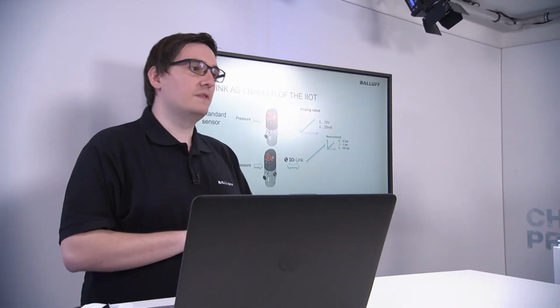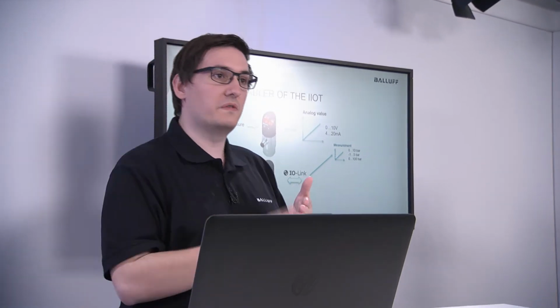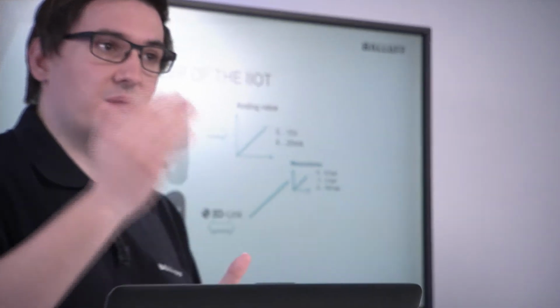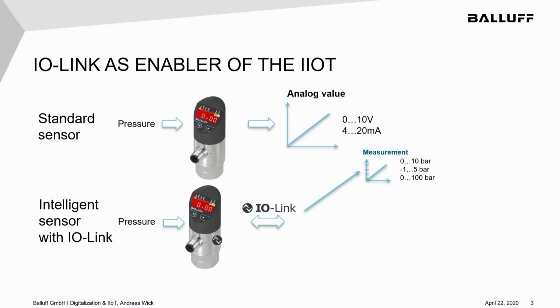As an example, an optical sensor which provides you with a switching signal is very good because you can detect whether there is an object or not. But if you want a software solution or a cloud application to use this value to measure over a very long period of time whether your belts are running in the correct order, or whether the speed of your wheels is correct and in the correct timing, these are very high-frequency tasks with a lot of switching points per minute.